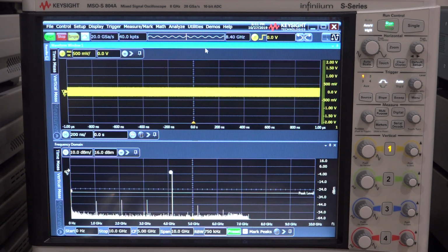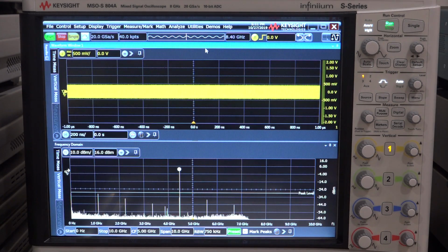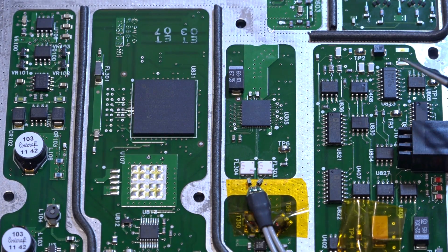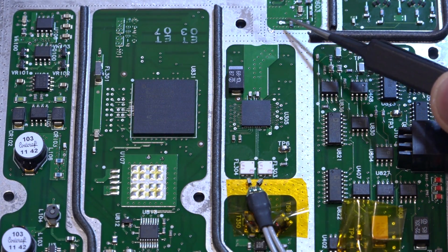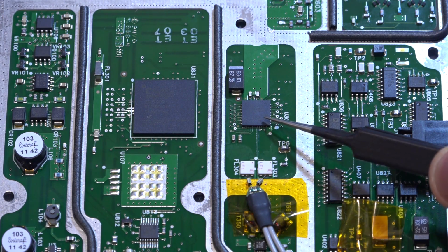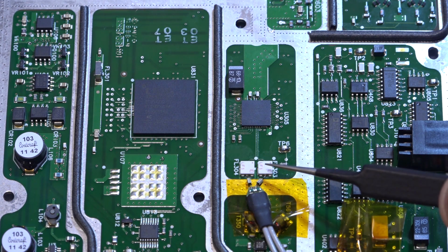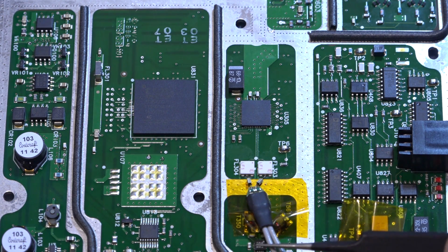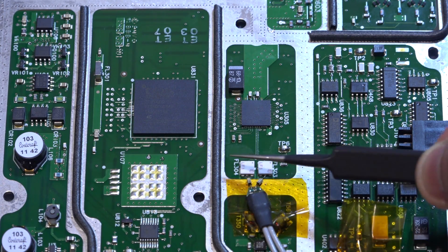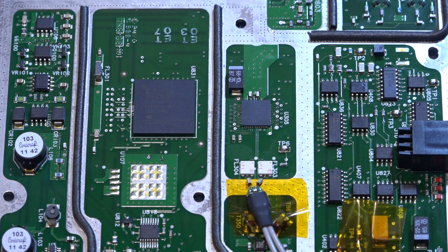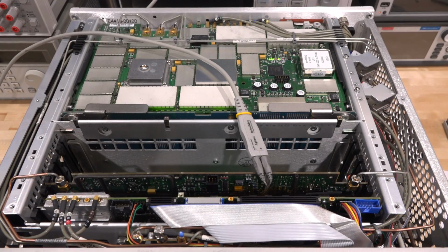Now it's going to become a little bit more difficult, because I was hoping that there'd be something wrong in the feedback path with one of the switches, but no, the switches are working just fine. So we have to keep digging. So we looked at the signal right here the first time, and that's the input to this ON Semiconductor programmable divider. And let's look at the signal right after it differentially across these two Mini-Circuits filters. After that, there's a mystery Keysight IC over here, which we're going to have to investigate. But let me see if there's anything unusual happening to this output when we cross the threshold of where the PLL stops working.